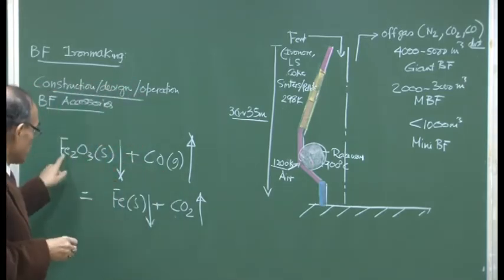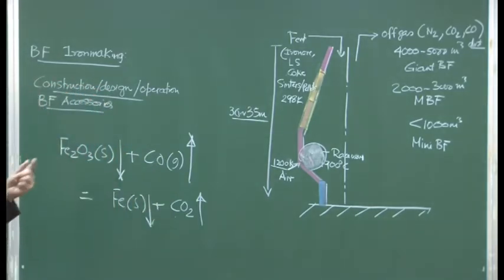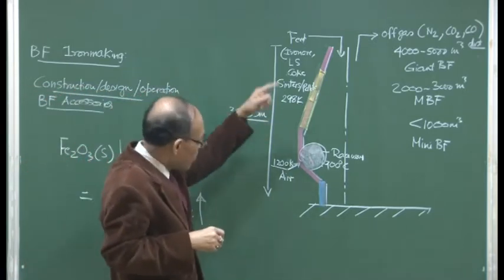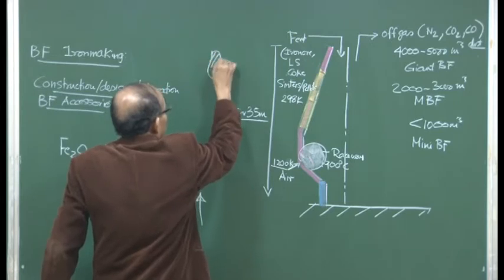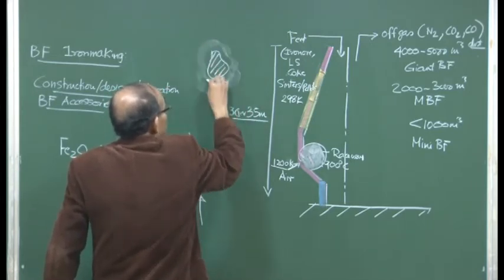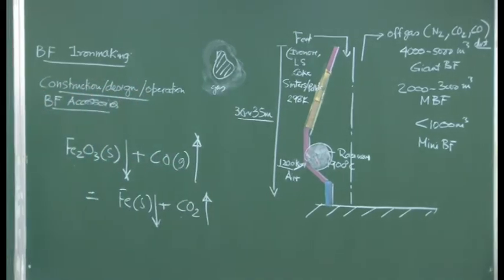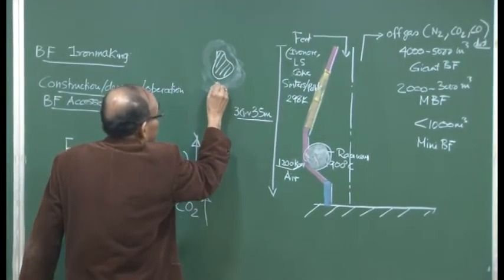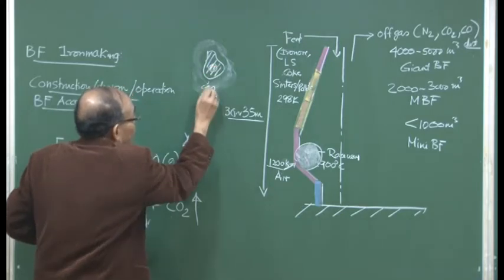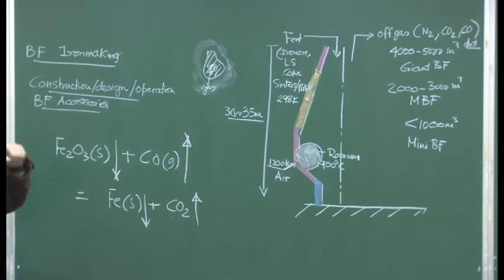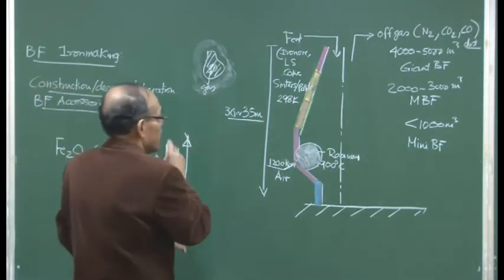So, the iron gets reduced, carbon monoxide gets oxidized, and as a result iron is produced. That is roughly the principle of the counter current reactor. In this journey, the pressure and the contact time are very important. The gas particle ascends and the solid particle descends, surrounded by various kinds of gases. So, the contact time of carbon monoxide with the solid particle is very, very important. Also, the characteristics of the solid are important, because the gas has to not only react at the surface. The iron oxide will be sitting somewhere inside, so the gas has to go inside, catch this iron oxide and reduce it. So, the characteristics of the ore, the contact time, etc., are very important parameters as far as the efficiency of chemical reaction, or iron production, in the blast furnace.